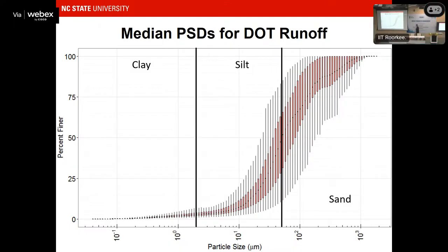What's good about sands relative to silts and clays from a sedimentation perspective? What's that? I think I heard what you said. It settles faster, which means the more sand you got, the more effective sedimentation is going to be. All right? So that's pretty good. About 50% of it was sand, and only a very small fraction, less than 5%, I think, on average, was clay, which is basically about impossible for us to remove.